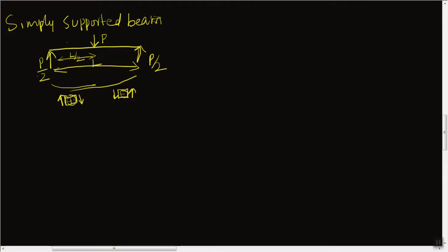Okay, and the net sign of the shear force diagram must be positive here in this case and negative here in this case. So our final shear force diagram will be like this. Since this is positive, it will continue till here, and here we are having negative shear force of the same magnitude. If I want the shear force at this location, I can consider this side of the beam, right?